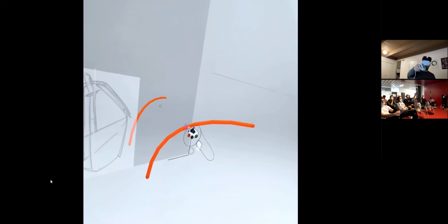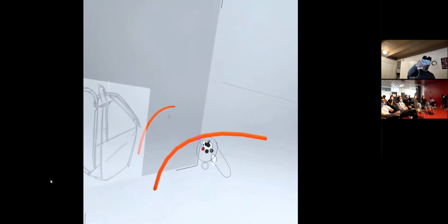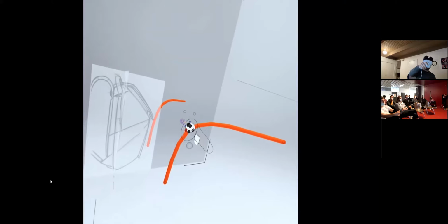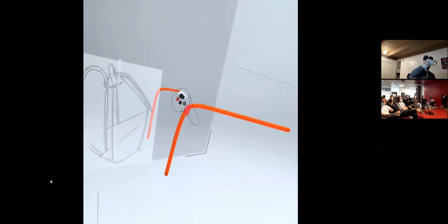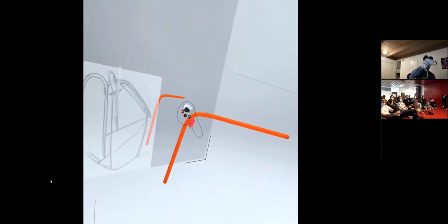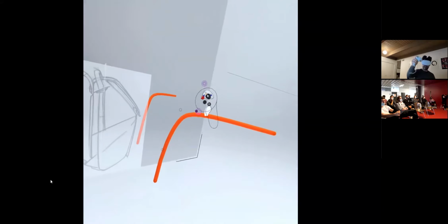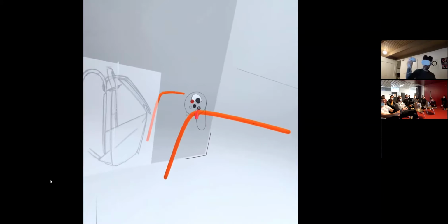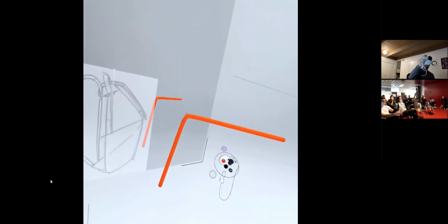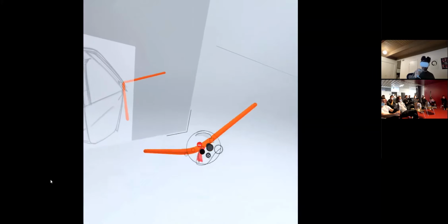And now if I want to have a corner or a radius, then I just do 3 points around where I want that corner to be. The farther they are from each other, the softer that round is. And of course, the closer they are, the tighter that corner will be. And this can be in any direction, like we showed before.